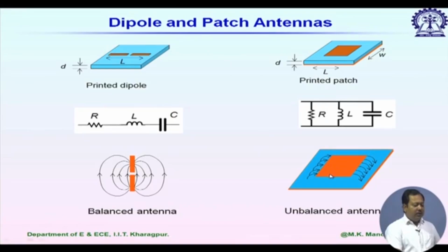Now, look at this electric field plot. We have fringing field on the left hand side and right hand side. So, it represents the length of this antenna in this direction. This length should be lambda g by 2 at the resonating frequency, and we will have maximum radiation intensity in the broadside direction of this antenna.